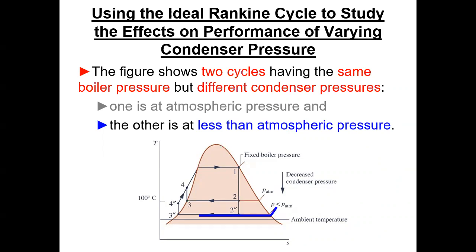And the answer is, wait till January. It's the only thing I can think that'll work. Well, and so as a point of fact, that plant is more efficient in January than it is in August, because that lake water is colder, and with colder lake water, we can get a slightly lower condenser pressure. So it's really the temperature that sets the condenser pressure.